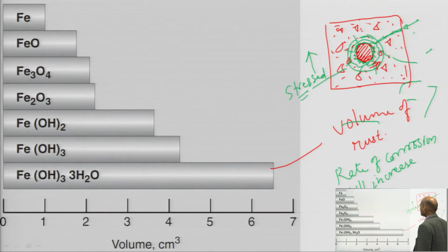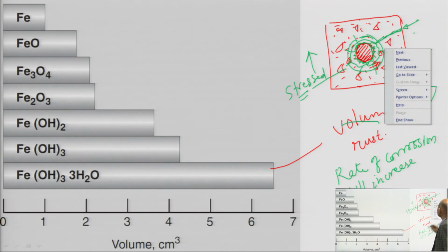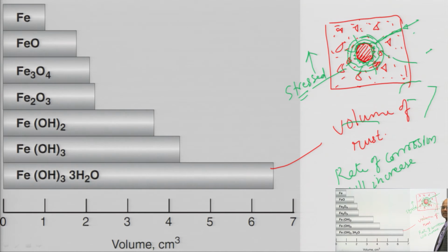Because concrete by nature is permeable, once you do not have a very good quality of concrete, what will happen? The rate of ingress, the rate of diffusion of materials like carbon dioxide, chloride, oxygen or sulphate into the concrete structure will increase, and this will lead to complete cracking of the structure. So, this is the phenomenon you can observe. By observation you can analyze what the cause of corrosion is.